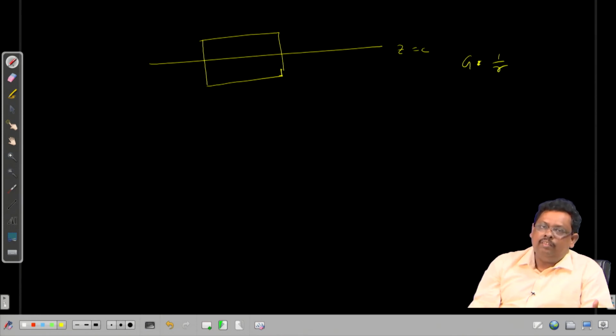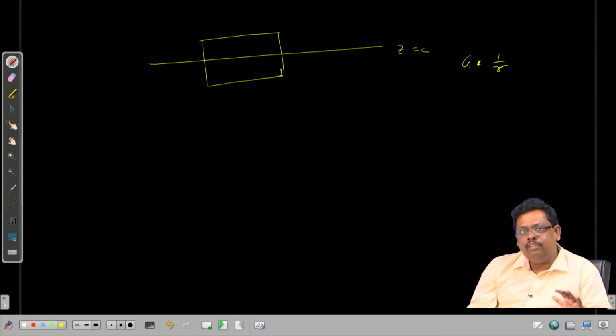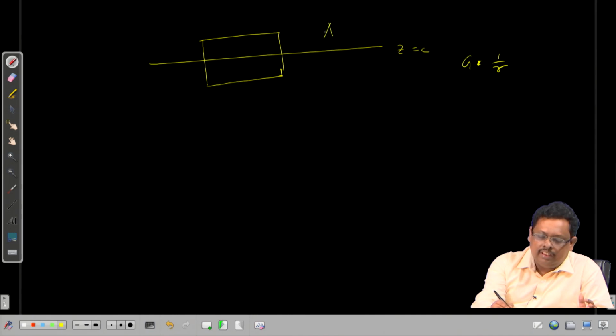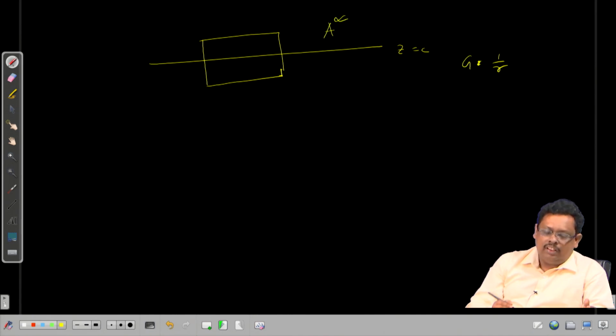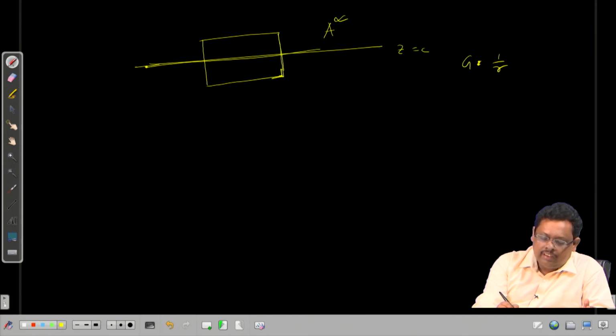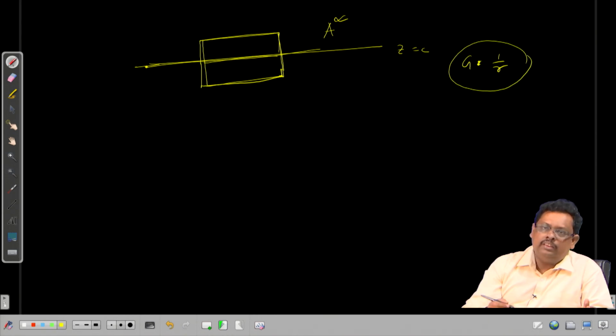You remember it, right, initially. So, I think that is the key. If you have that code with you, then this is your infinite added mass. Only thing, the geometry you need to put over here, and then it is the wetted surface, and you take the image part and solve this with this Green's function, and then simply solve this boundary value problem, then you get this infinite frequency added mass.